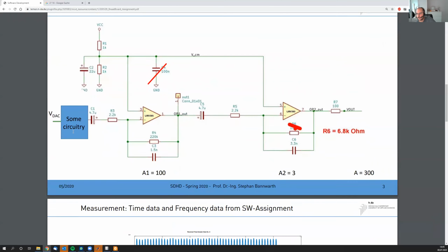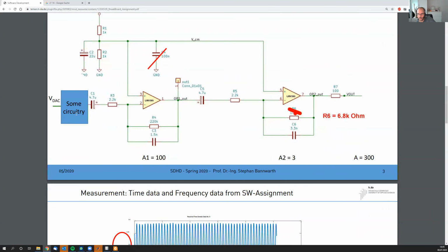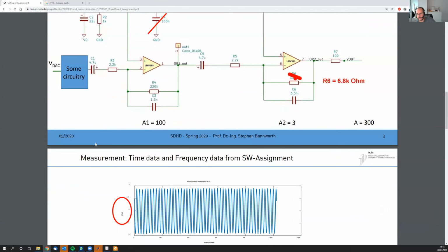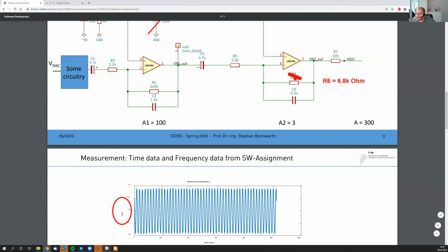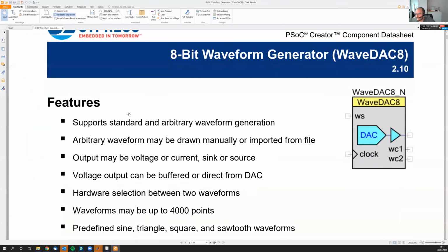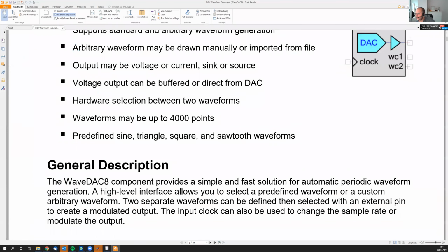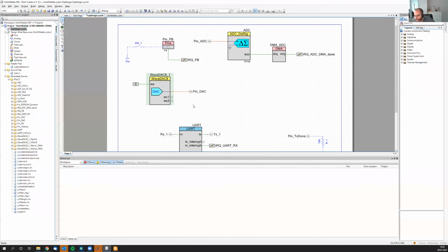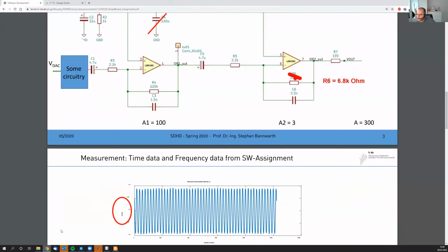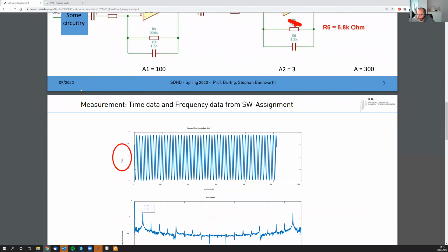So you have to be a little bit careful here, maybe not to use very high resistances, but rather low resistances. So don't stress that pin too much. You also might want to look maybe in the data sheet here to learn a little bit about the output and the electrical characteristics of that output. Yeah. So this could be a small problem here.